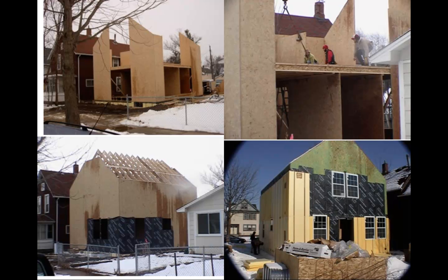So in building this, you actually use your second floor, or the I-beam to support the second floor, as a bracing system. So this I-beam, as I'm showing with the pointer, actually extends over, attaches to this wall, and keeps that wall from buckling out or buckling in.